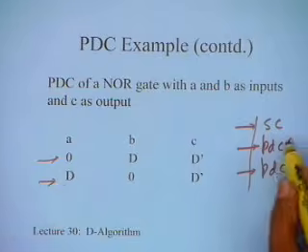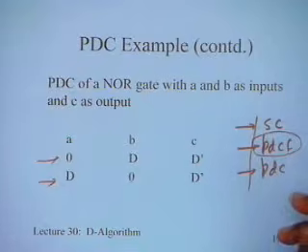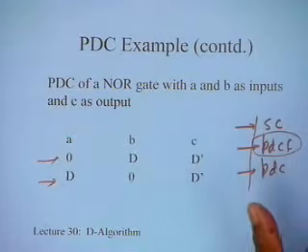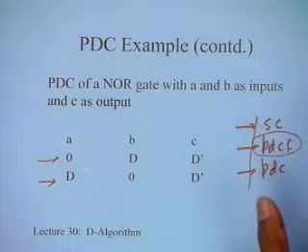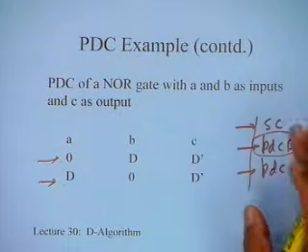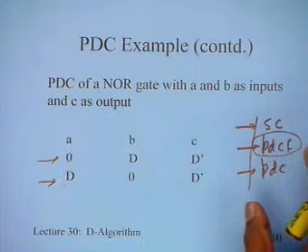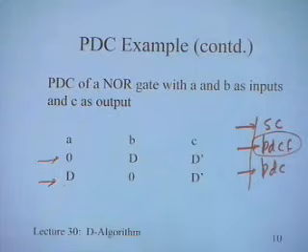In case of PDCF, of course, there are two types of entries here, one for stuck at 0 at the output, one for stuck at 1 at the output. And in each case, I could have again multiple rows. I have to choose one of these as required. And sometimes we will see that when multiple options are possible, then backtracking may be required if consistency fails. We will consider that in an example later.